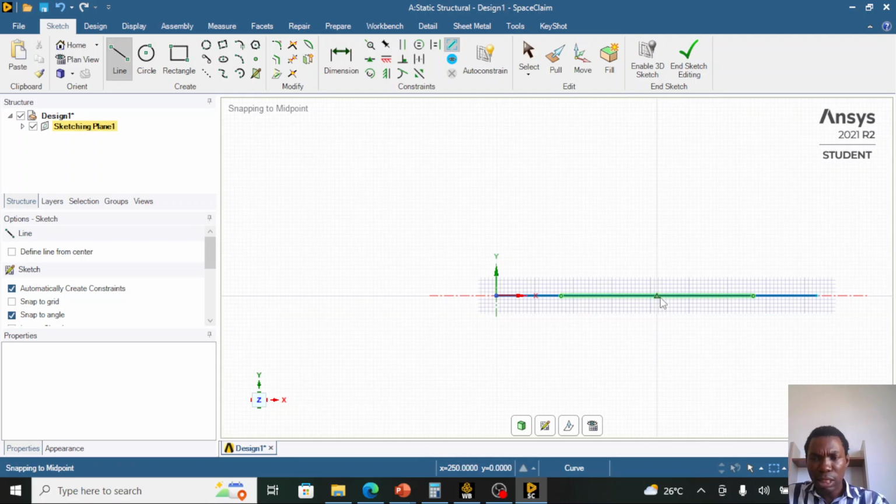I'm going to draw this line from above the full model, from the center point. Press Shift on your keyboard to reference dimension from the center node point of finite element 2. Go up. So I want to sketch my line.